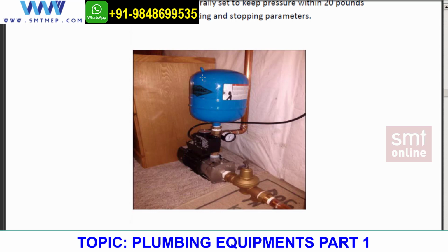To avoid all this, we need to calculate this pressure tank. And what is the function of the pressure tank? First of all, a pressure tank is something which has pressurized air inside. If someone is calling for a limited amount of water, for example for a lavatory or a kitchen sink, not a huge amount of water like for bathing, it will not allow the pump to turn on because the water is under pressure, as the air is compressing from the top.